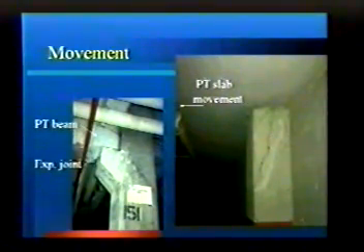And you have a post-tension girder on this side. Well, due to water, salts, and corrosion, the slide bearing froze. And they tried to repair this thing multiple times. And this is patch after patch. And finally, we took a look closely at the bearing itself. Okay, we freed the bearing. Now the patch works fine. Okay, again, it's the source of the problem. Go back to the source.